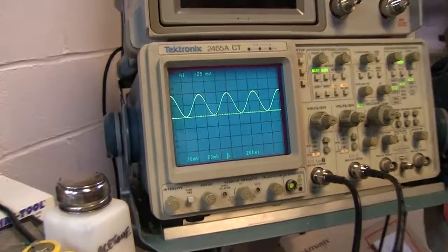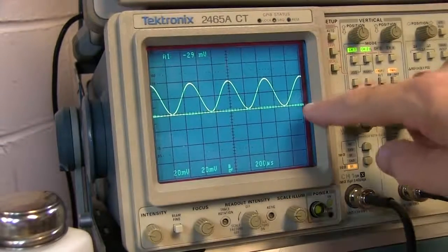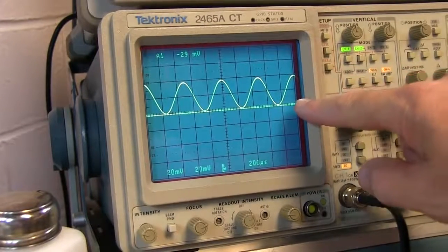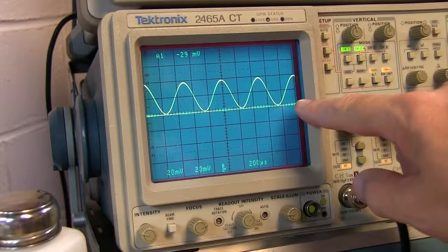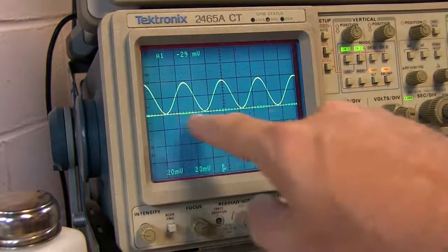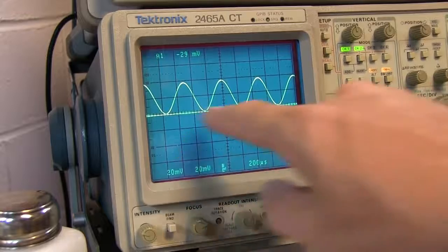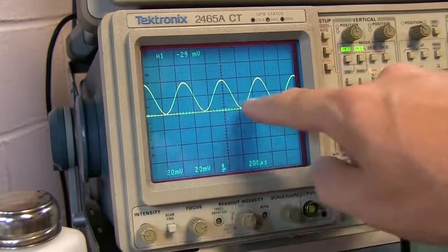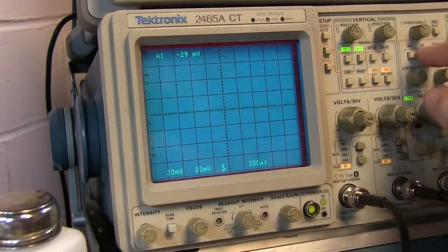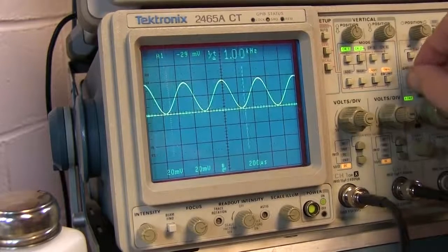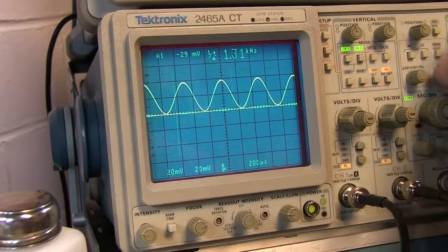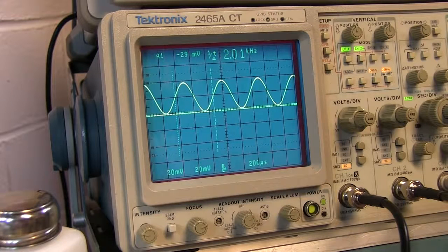The scope is displaying both the I and the Q components. As I mentioned, I've got the phase aligned so that there is no I component at all, so we see the DC on that, and I can see the Q component varying sinusoidally. If we put a set of cursors up here, we can measure that baseband frequency right around 2 kilohertz, just as we expected.